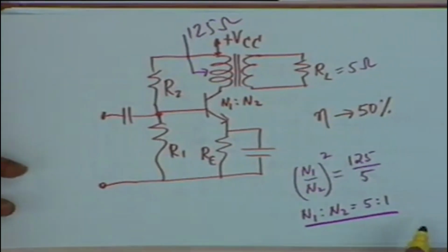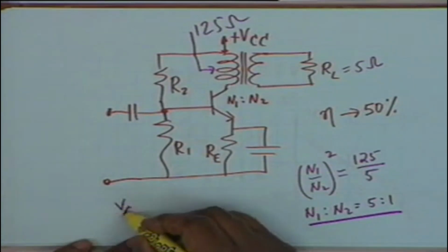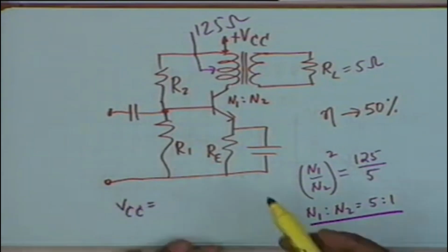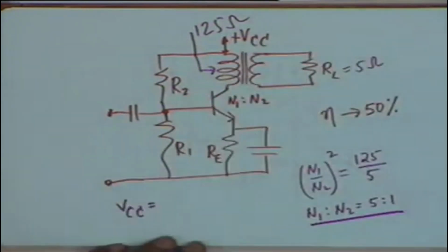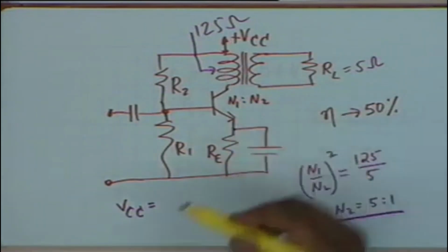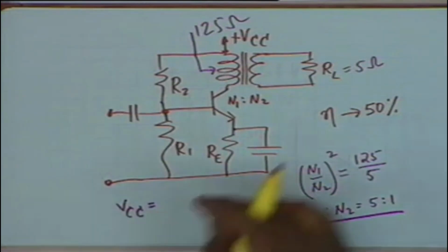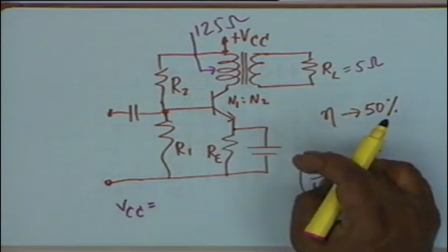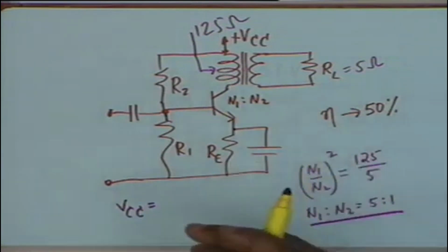Now under this condition, what VCC shall be needed? Well, to determine VCC, you notice that the transformer primary, because of zero resistance, we assume it to be ideal, does not drop any voltage, and therefore the only drop that shall occur shall be across R sub E, and you can set this drop almost arbitrarily, and as I said, 3 volts, 2 volts, these are typical figures.